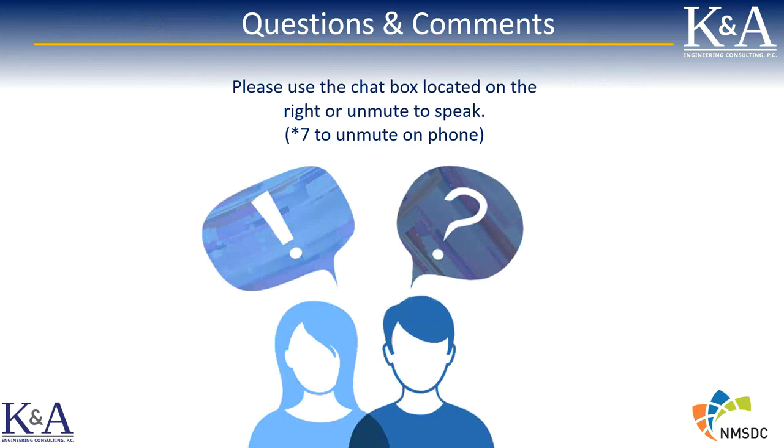We're actually working right now with a virtual reality company that is creating a simulation of a substation, and they have, for example, a training module that shows the technician going through a step-by-step procedure on how to do a bus transfer, which involves closing isolating switches and circuit breakers and grounding switches, and they have to be done in the proper sequence.